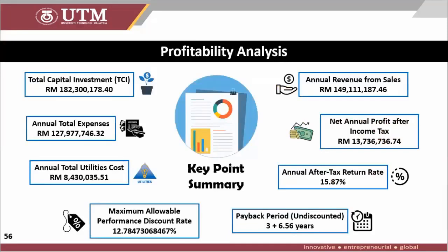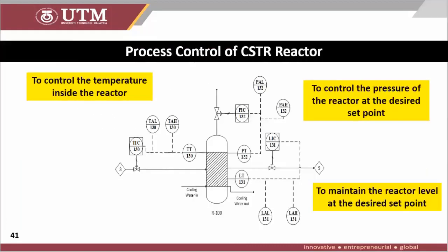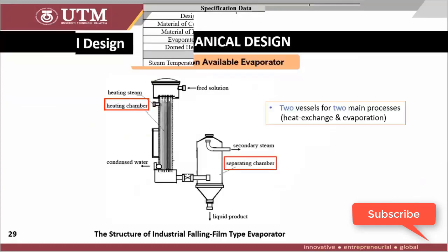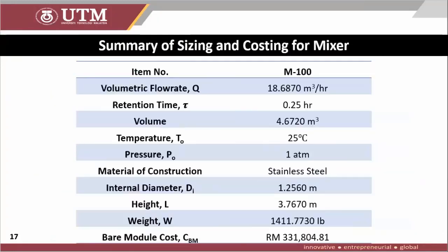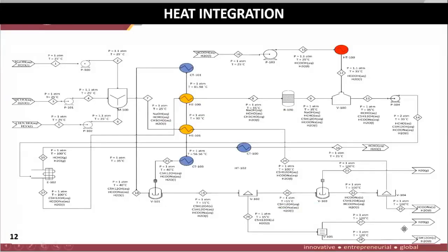Crystallizer. Okay, stream 28. Then after the crystallizer you have a dryer, right? Yes. But your stream at 120 degrees C still contains water, right? So you dry at 120 degrees C at 1 atm. Based on the basics, that means all the water is removed. Yeah.